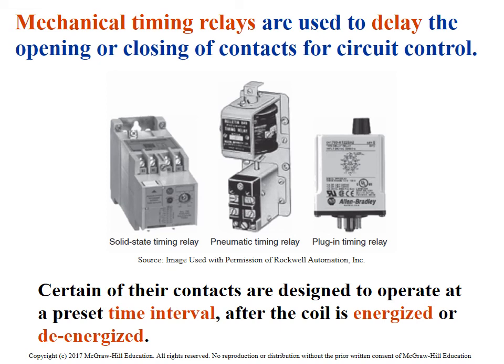And so the use of these is getting less and less all the time, just because of the flexibility of a micro PLC, or they even call them smart relays. If we were in the lab, we would see it was called an 810, which is basically a relay with some push buttons on the face of it and a digital display. It allows you to set up things like timers relatively inexpensively, as well as a pretty easy setup.